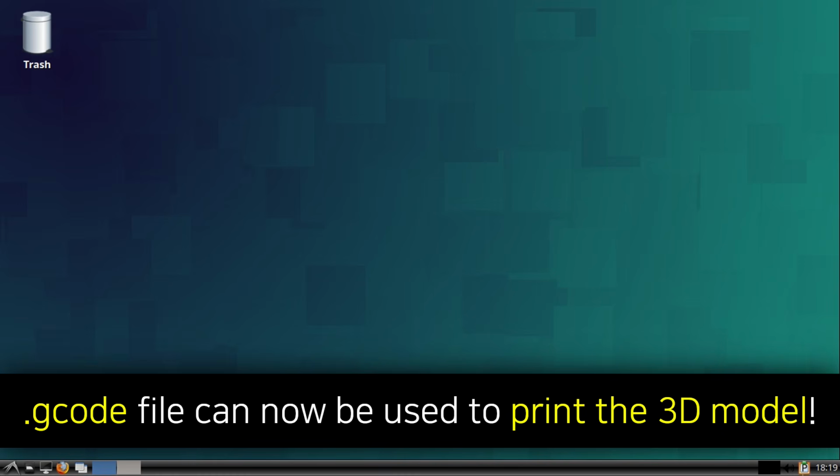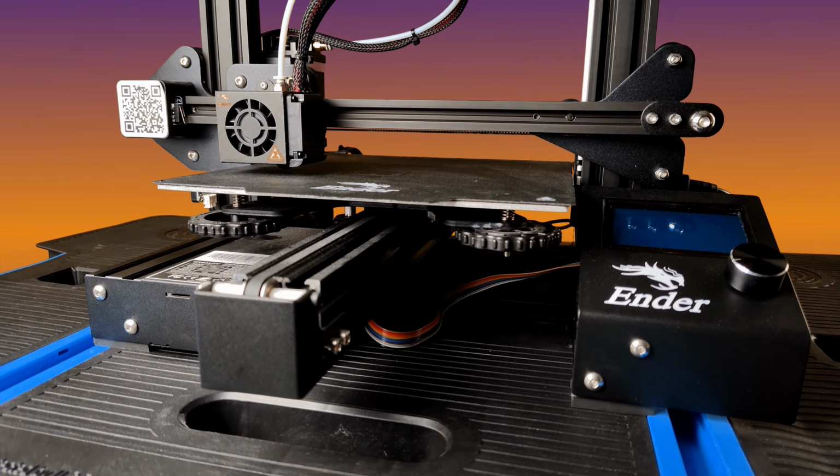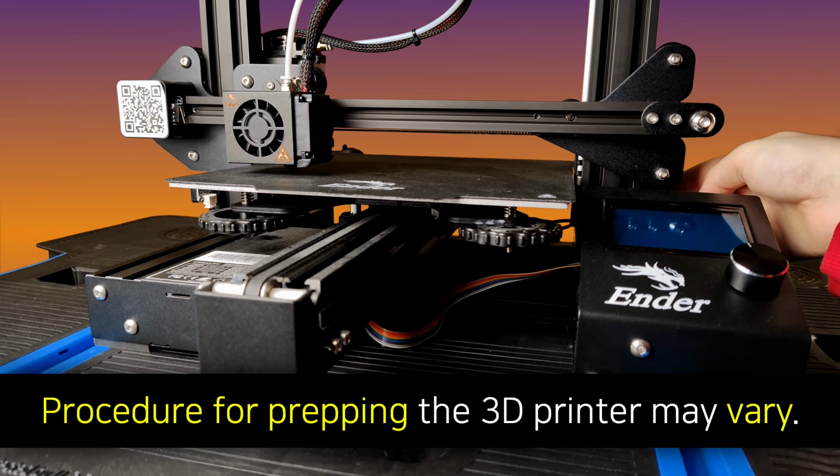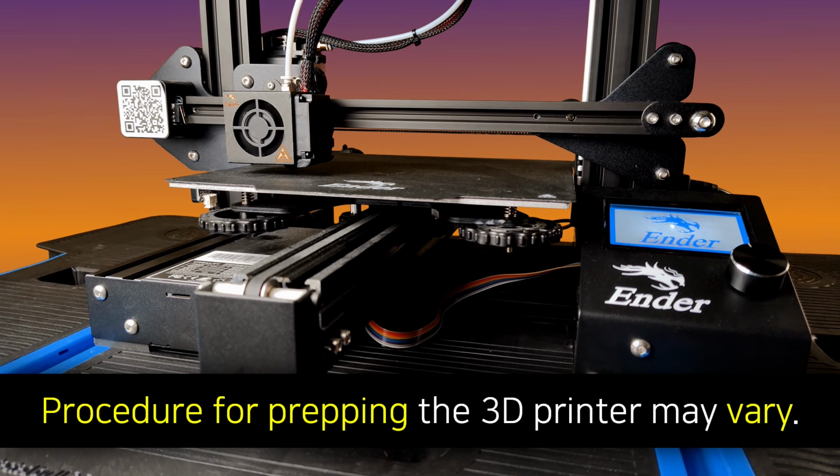So now we can use the .g code file to print the model. Now we can 3D print the cube. For my example, I am using the Creality Ender 3 Pro printer, which I've had for a few years. Keep in mind, your printer may vary on the procedure needed to prepare for printing. So this is just a general example of how I prep the Ender 3 Pro.